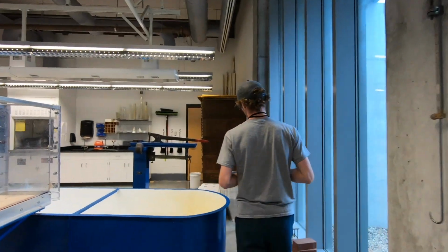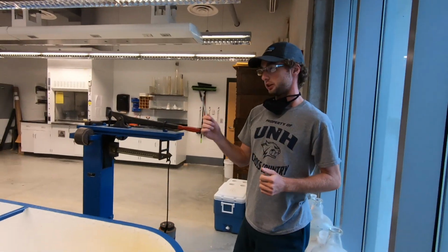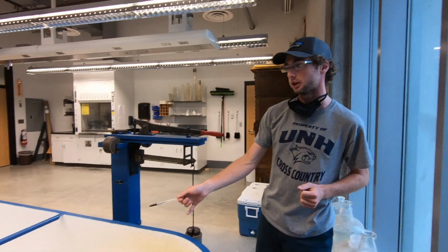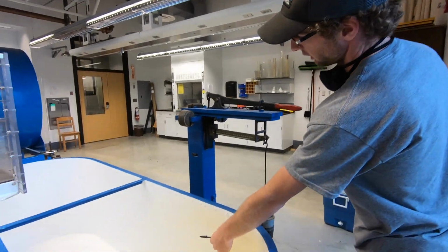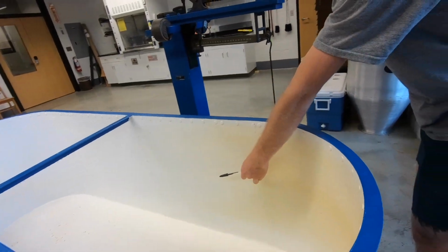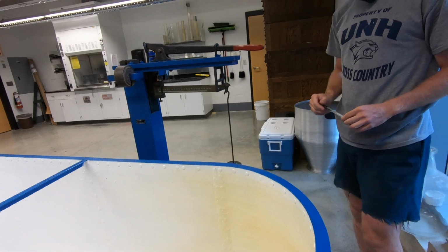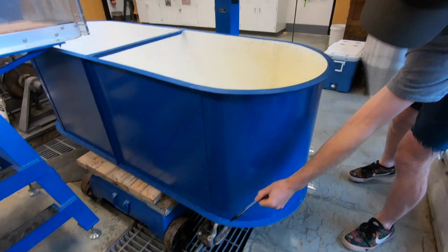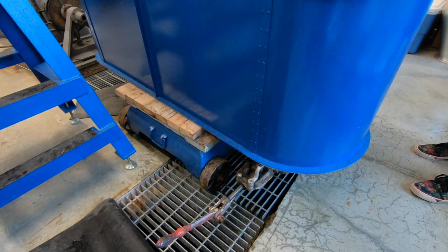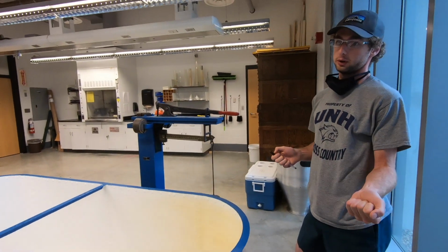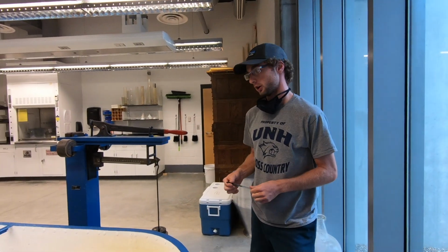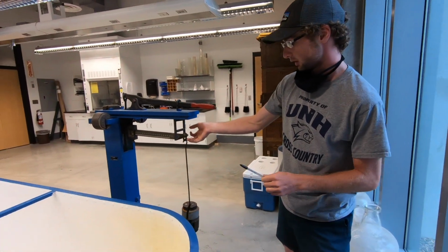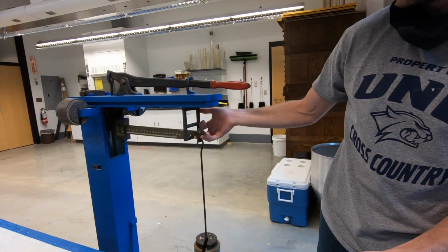For our last way of measuring the flow, we're going to be using the weigh tank here. When we're running the trials, the water is going to be sitting at a level within the tank. Essentially what we're going to do is use the valve down there in order to stop the water from flowing out of the tank. We're going to shut the valve, closing off the bottom of the tank, and we're going to wait until the tank is heavy enough such that the weight here